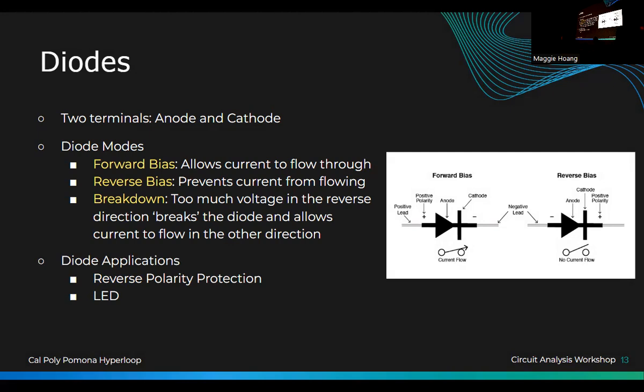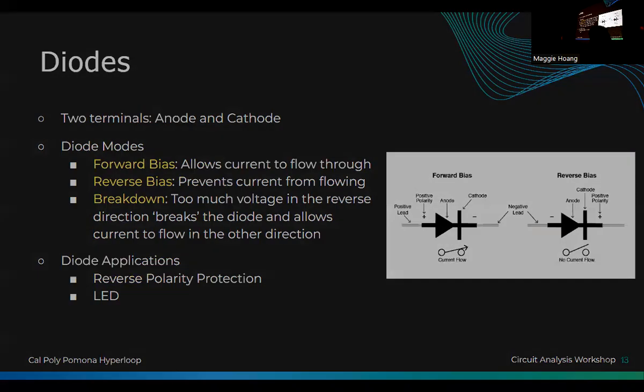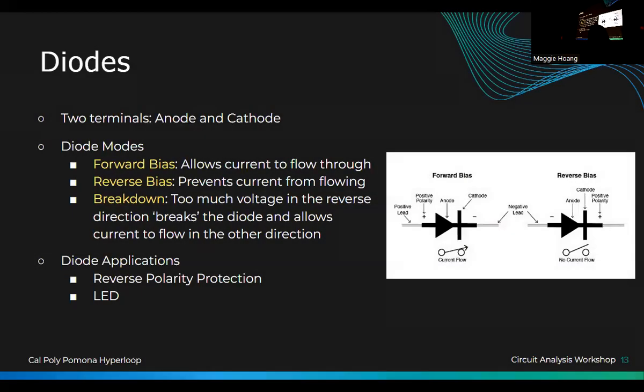That's why when you plug an LED into your breadboard, you have to put it in the right polarity. And when you're using diodes, there's a cost: the current can't just go through for free. You have to pay a cost of around 0.7 volts to go from one side to the other, right?